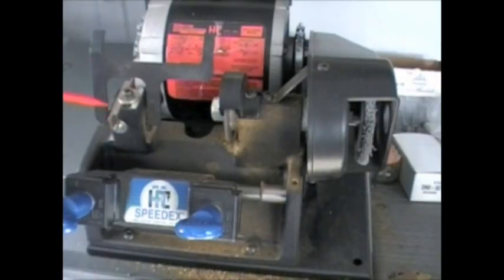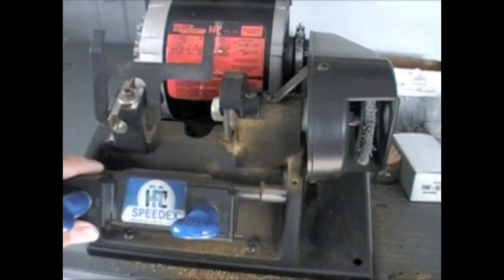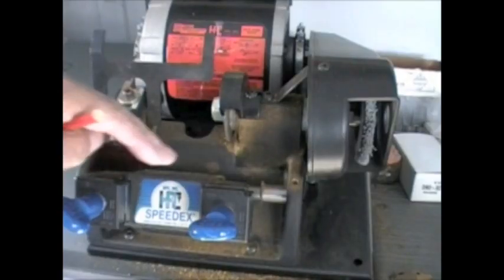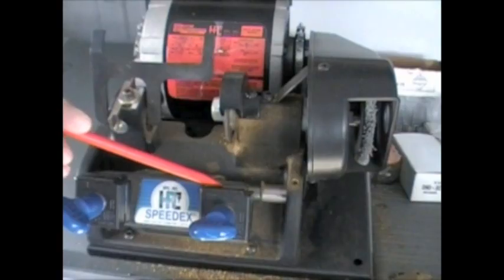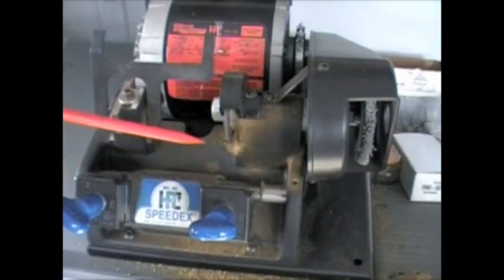This piece here is the tracer or the guide. This is the tracer lock nut. Down here we have the tracer depth adjustment, and I will show you how to use that. Then we have the carriage here on the front. On the carriage there's two jaws, often referred to as vises or blocks. Normally the key you want to duplicate will go in the jaw on the left and the blank will go on the right. And so those are the basic parts.